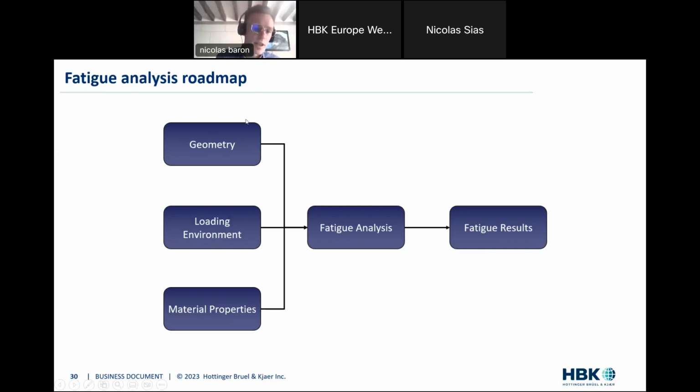These 3 inputs are key, of course. Geometry, loading, very, very important. That's why it's very important to characterize as much as possible the real loading conditions for your components. If you don't have the real loading environment, chances are you're designing in a way that's not robust. You might be off the picture because you are not calculating with the loads that your components will have to withstand once released in the field. And the final input, the third one here at the bottom, is the material properties.